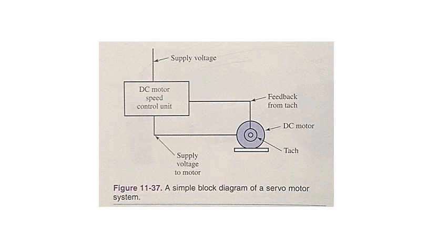As an illustration of the servo motor, let us assume that a motor is required to operate at a constant 1000 RPM. After the motor has been running for a period of time, an unusually heavy mechanical load is exerted on the motor. As a result, the motor's RPM drops to 900 RPM. As the motor slows, the tach also slows down and sends less voltage back to the electronic speed control. The electronic circuitry now increases the applied voltage to the DC motor until 1000 RPM is regained.